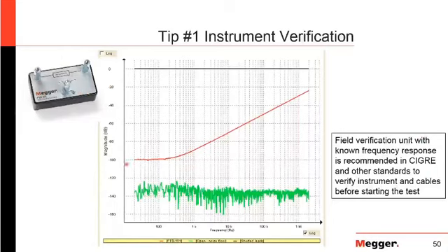If for some reason you forgot this thing, there's some other tests you can do to check. One is shorting the leads together, and then you'll expect this typical 0 dB response. So very little change between the output and the input, especially when you look at the full scale here. And then the other thing you can do is an open test, just to check the noise floor of your instrument and see, okay, if we keep the leads open, don't connect anything, where are we getting noise here? And you just want to make sure that's well below the range that you're measuring on your transformer.